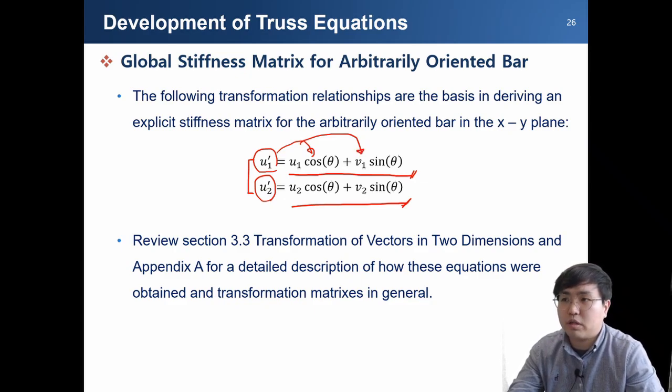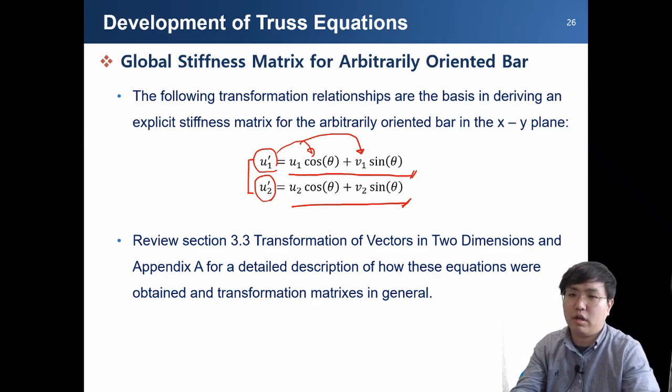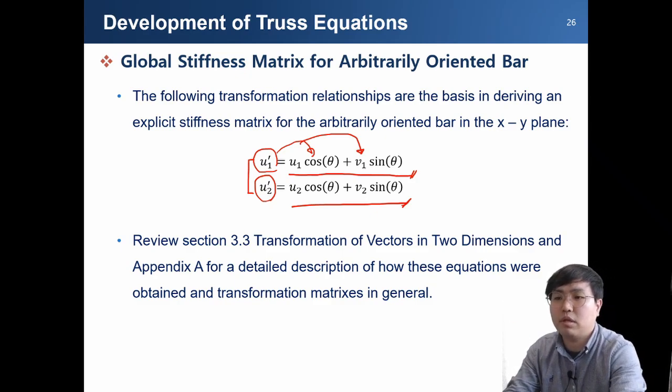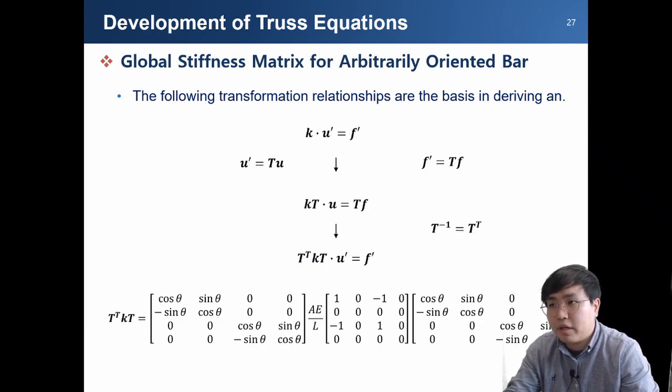Depending on your convenience, we can consider only the x-axis displacement in the local coordinate system, or you can define the y-axis displacement in the local coordinate system, and then you can change both x and y to the global coordinate system using the transformation matrices in the previous slide. So anyway, we have a stiffness